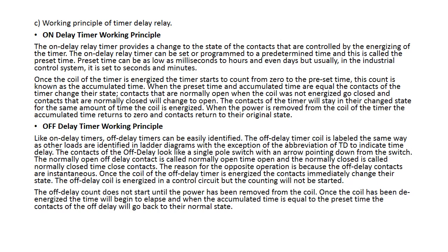So the off delay count does not start until the power has been removed from the coil. Once the coil has been de-energized, the time will begin to elapse. And when the accumulated time is equal to the preset time, the contact of the off delay will go back to the normal state.